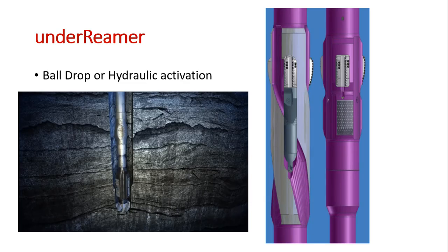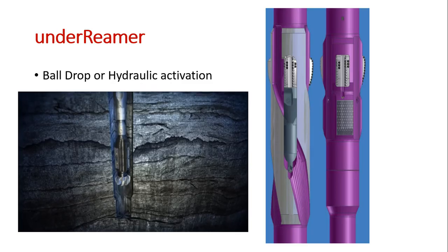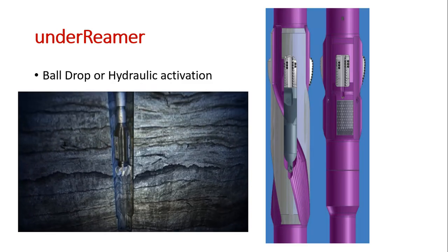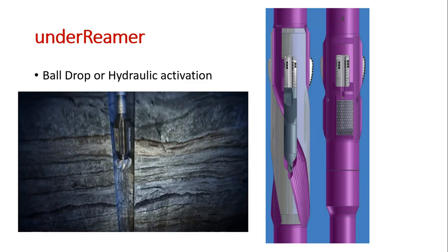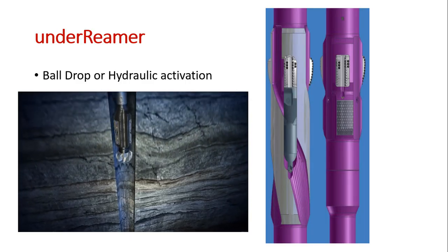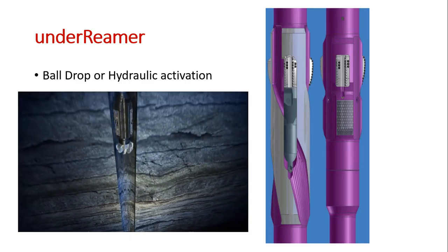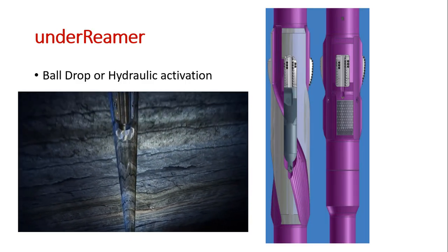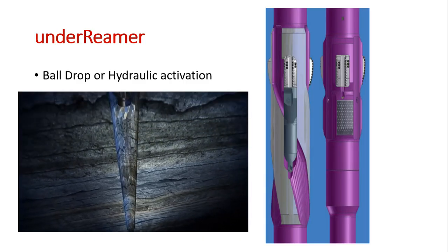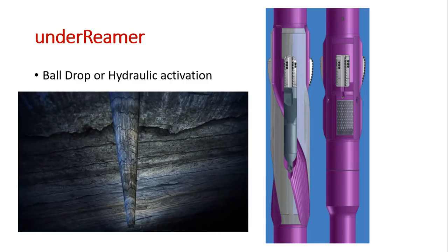And the drilling assembly can be pulled out of hole, and casing operations commence without the requirement for an additional dedicated reaming run. The TD Ream tool was developed to save operators time and money, demonstrating Halliburton's focus on solving customer challenges by applying reliable technology in innovative ways.